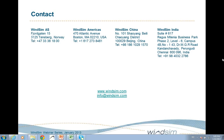But as long as your data set extends enough in all directions, you should not have any problems to use the SRTM in the surroundings. What you of course have to be careful about is that you always normally have merging effects. So you have to see if you have some sudden jumps in the terrain height or in the elevation.